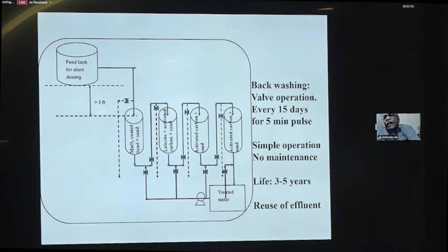Okay, so rice mill effluent contains lots of organic material. So we do a primary treatment where the organic material is deposited and it can be taken out. And after being completely dried out, it can be used as manure and as compost fertilizer. The leftover water is passed through a manganese dioxide coated sand bed, through which the leftover organic material is completely demineralized and oxidized.